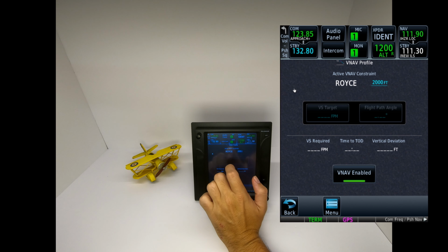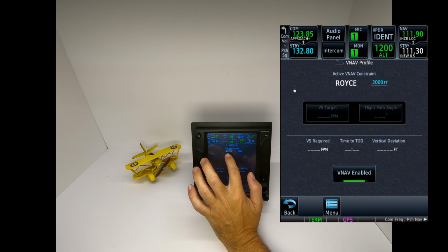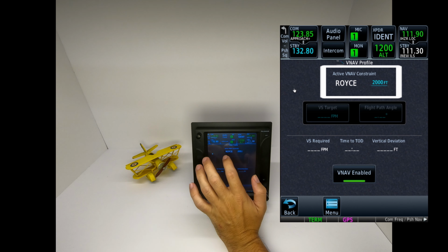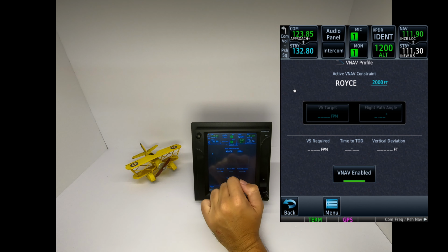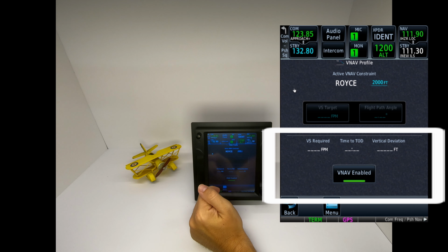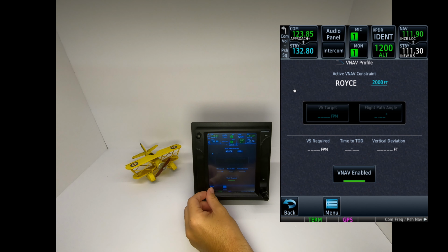Say, just to give you an example, we're flying back from Houston to Lakefront, and Harvey is my last waypoint. I can set up Harvey here, and then say, let me be at Harvey at about 3,000 feet. I can set 3,000 feet on here, and down here it's going to tell me my rate of descent, and also in time. Now, if you have a VNAV button on your autopilot, it's going to start descending with it. If you don't, then this is something you manually have to set.